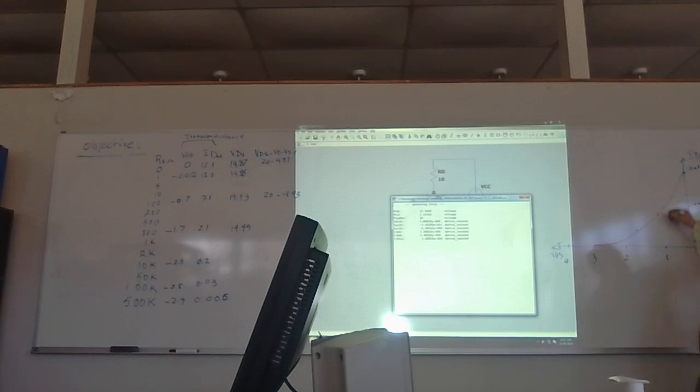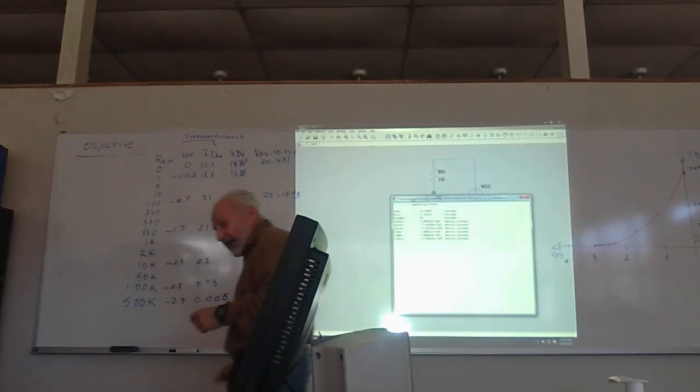And we usually like to be right somewhere around here, the upper 1/3. Why? Because when you do a tangent, it's steeper there. So you have a better deflection of the input signal to the output when we're ready to do AC. Do not worry about AC yet. You with me so far? We're still in the DC world. Just know that it's on purpose so we can have an operating point that will ultimately give us the optimal control of the signal, the AC signal, from input to output, especially when you're using it as an amplifier.